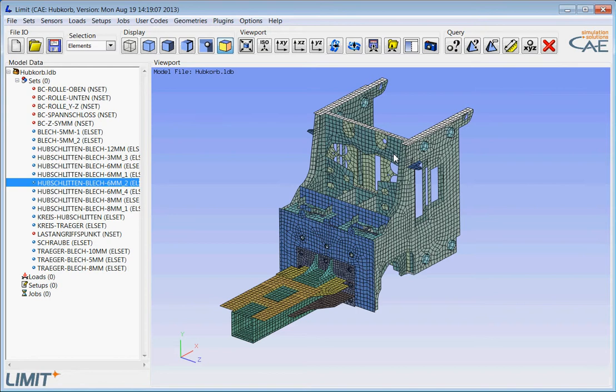Now, if we talk about a welded structure, every part or every area where different shell properties meet are potential welding areas, and using the information on the shell properties, we can automatically derive these element sets from the structure.